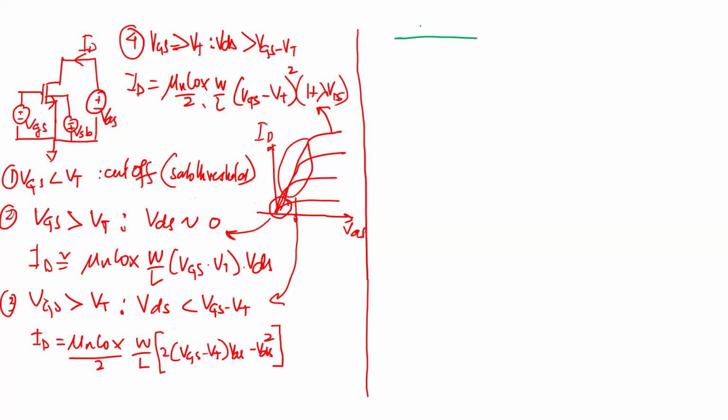So if you have a VDD, NMOSs here were referenced to ground. PMOSs are usually referenced to VDD. Okay. So if you have a PMOS here, it'll look something like that. You've seen the symbol actually, which has the bubble and the arrow as well. Typically, you either find the bubble or the arrow.